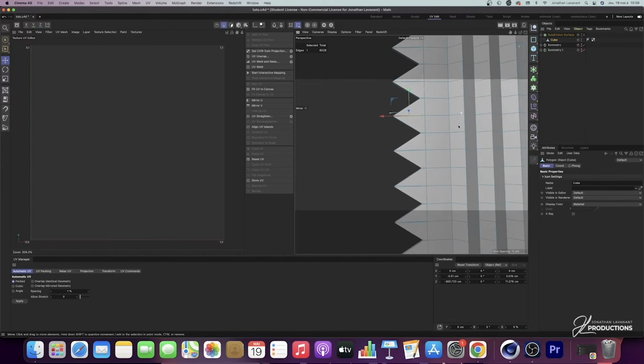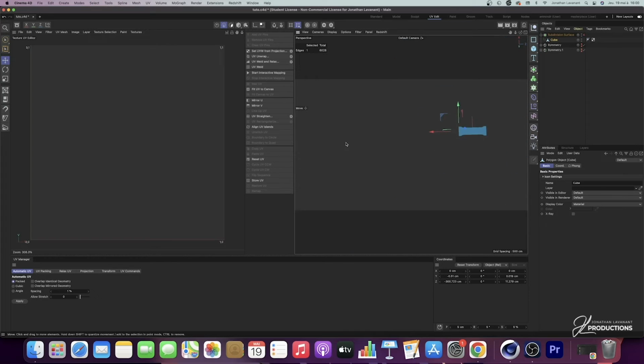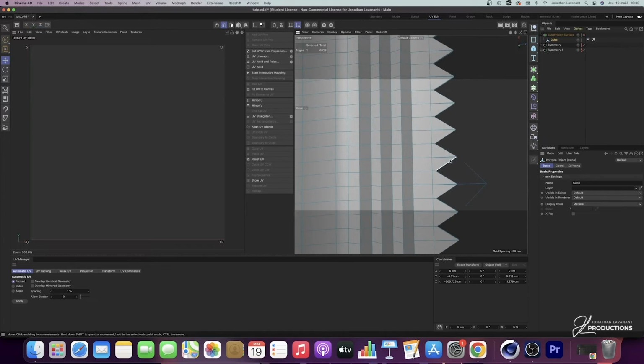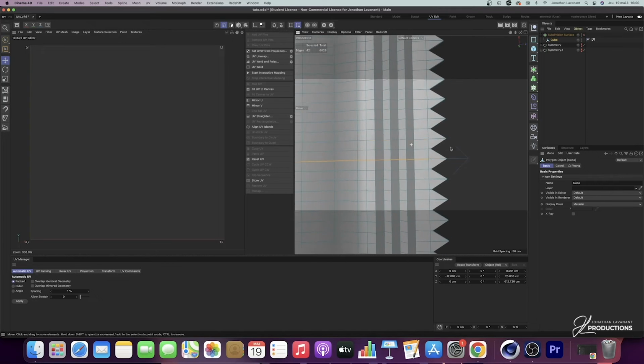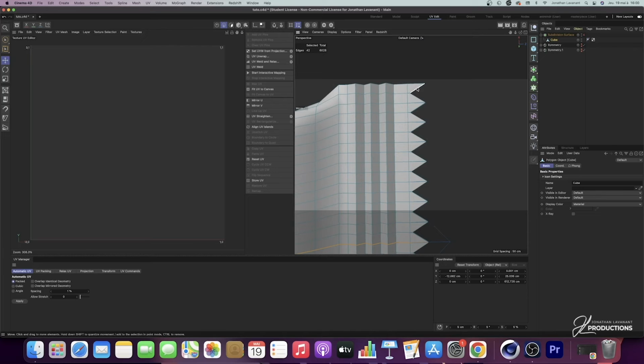I'm going to put myself in edges mode. I select in cubes and I just select the one in the middle, and so there. I'm going to put the opposite, and I'm going to do exactly the same thing to be able to link the loop of the middle and create a cut in the middle of our bar. So here, I'm doing Shift and Control to be able to create a loop in the middle, and I'm going to do the same on the side.